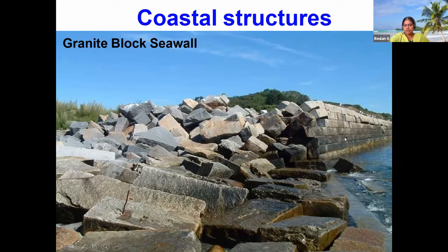When you create a member which is exactly perpendicular to the shoreline, the interlocking between these members should be strong enough to resist undermining. Do you know what undermining is? The water will penetrate inside the lower regions of the wall, and may have a tendency to destabilize the member which is placed in the top region. So the height of the seawall is determined based on the high tidal wave region.